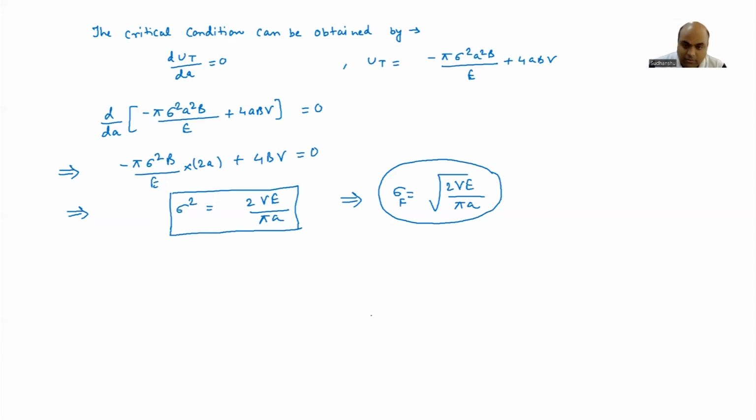Okay. So this is the crack propagating stress. Okay. And one thing you can note, right? There is an inverse relationship between sigma and crack length. So if the crack length is higher, sigma F is going to be lower, right? And why is that?